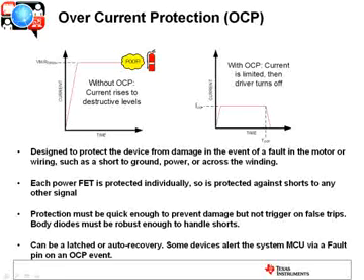The body diodes also have got to be robust enough to handle the shorts. You don't want the body diodes breaking down and the device being destroyed because the body diodes can't handle it. So typically the motor drivers have the on-chip overcurrent protection built in. They are monitoring each individual FET, so you're fully protected against these shorts. When an overcurrent event occurs, the fault can either be latched or auto recovery.